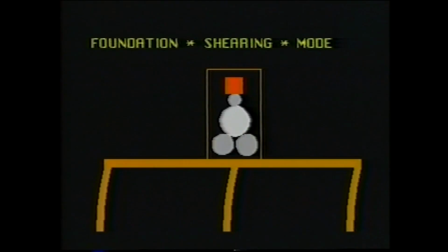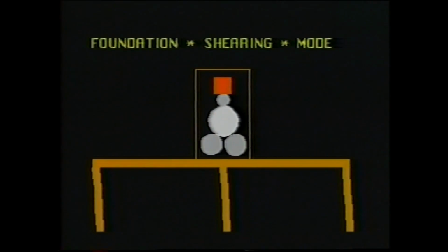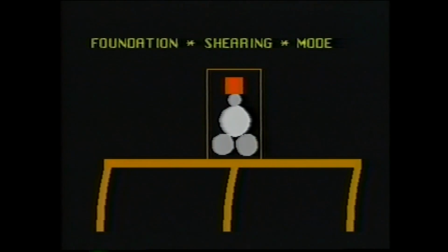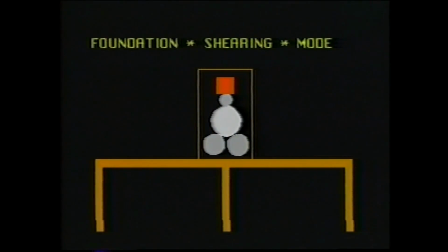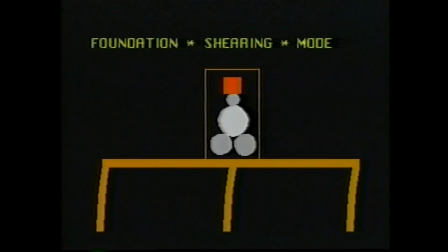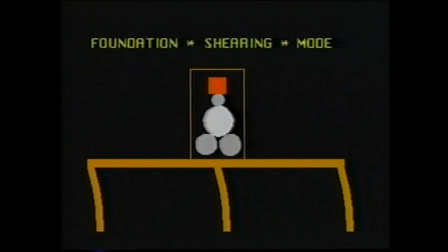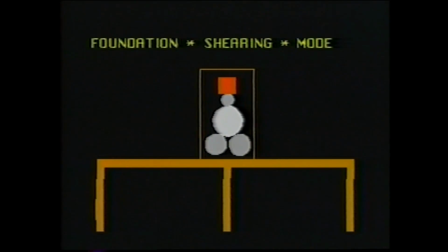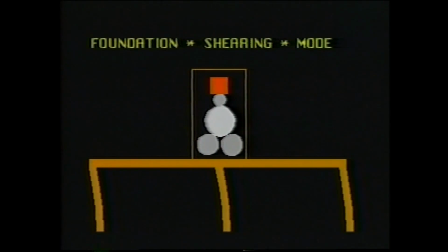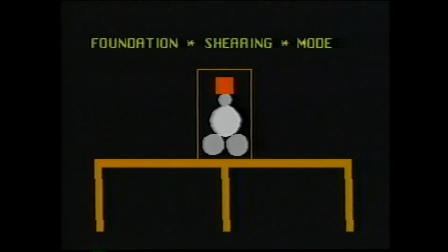We cannot design foundations such that all resonances have a frequency greater than the exciting frequencies in a winder. We can only minimize the number and severity of resonances. A conservative design approach would be to specify 2 continuous walls underneath the winder base plates, spanning from the unwind to the front drum. The alternative, which can be more costly, is to commission finite element modeling to optimize design.